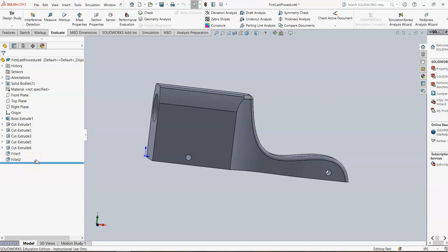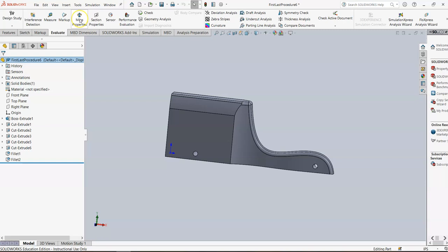All right. Remember, fillet is the last thing that we're going to do. And if you have to go back and make any changes, I would delete the fillets and come back and add them again because they are very quick to add. Fillets take a lot of math to calculate, and if you end up with a weight issue and you've got to go back and fix your car, what inevitably ends up happening is you're going to have a problem with a fillet. So I usually just recommend everybody delete the fillets if you have to go change and then just add them in again. The final thing that we want to do is mass properties.